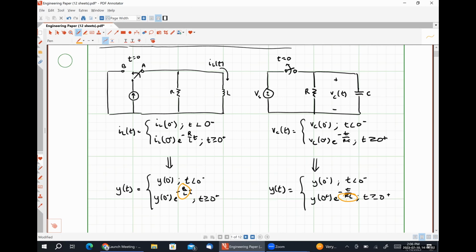So people much smarter than me came up with the idea of a time constant to formalize this rate of decay for first order circuits. Effectively, if a circuit is decaying at some particular time constant, it does not really matter if we look at it as an RL or RC circuit. We're just looking at its exponential decay.